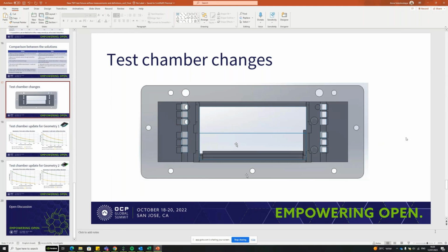That's good. Jonathan, I haven't checked my email yet. Do you have the 2D DXF ready for me? Not yet as of now. If we're okay with the change there, then I can generate all of that. Okay. The earlier one you provided, when I gave it to the lab folks, they said they want something from before the bend because they want to laser cut prior to the bend and then they can bend it. The one that you sent to me is already bent, so they don't know how to unbend it.